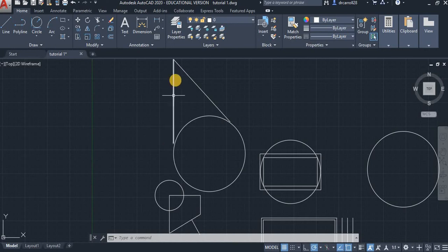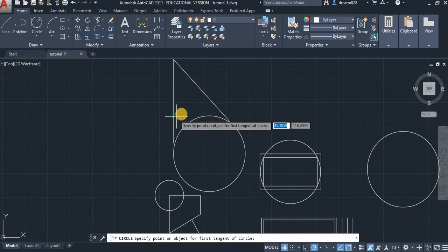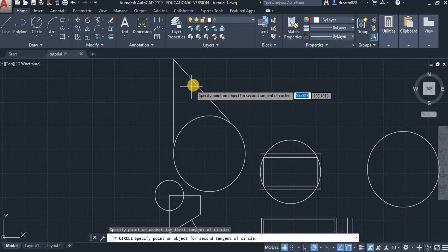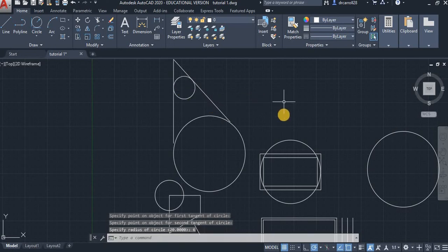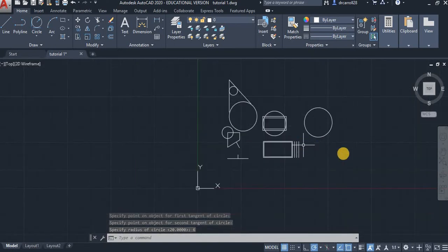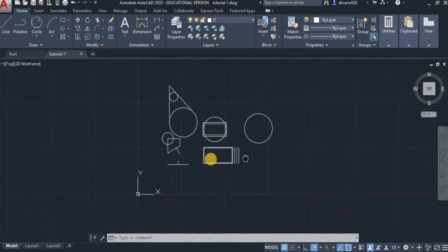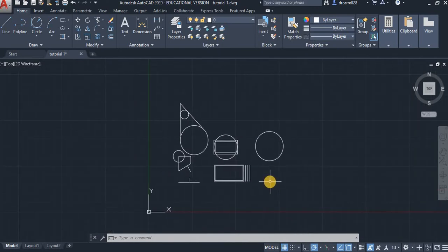So do another circle, repeat what I just did, but now make the radius 6, let's say. Okay? Try to do that yourself. Here's how you can do it. Click this again. I want the circle to be tangent to this and this. And now let's make the radius 6. And there's that circle. Okay? At this point you should have drawn all these things that I've drawn right now. Press pause if you haven't done that and make sure to draw all these objects.